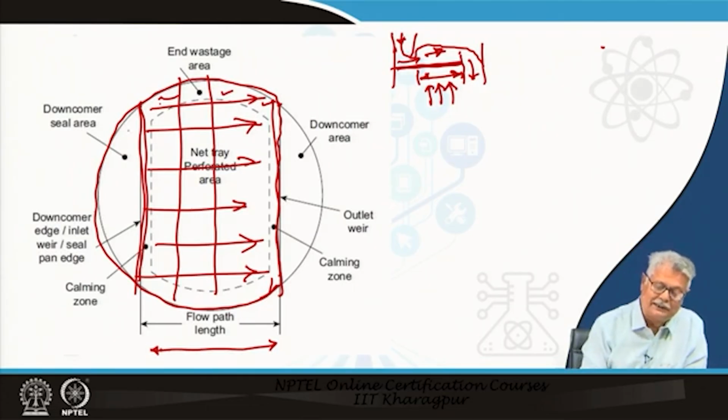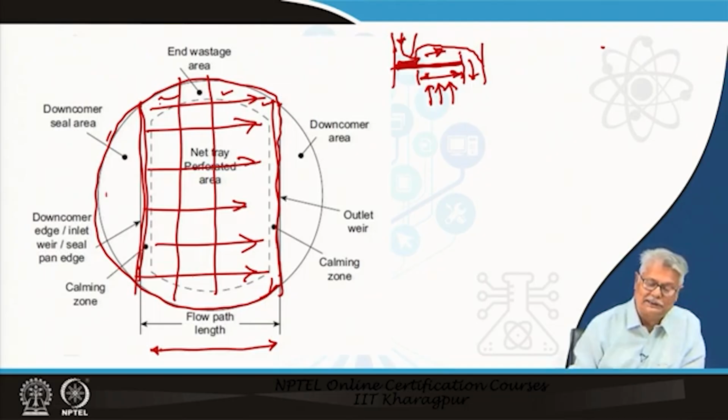It is obvious that this portion will not have any perforation. It will have the fixing arrangement with the tray support ring, and naturally, since this is the area which is under the downcomer of the upper tray, this is the downcomer seal area. There are downcomer seals which are provided, there are downcomers without the seal also. The seal we will see what exactly it is when we go to the further diagrams.